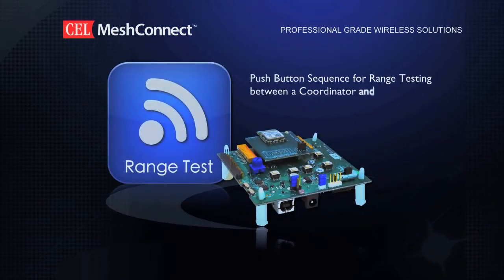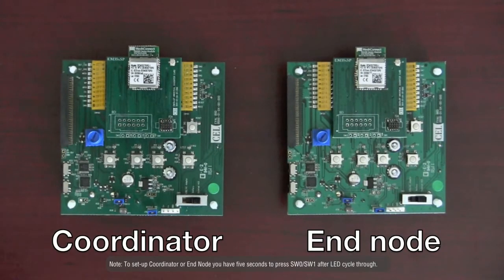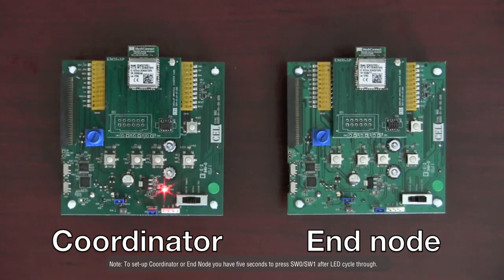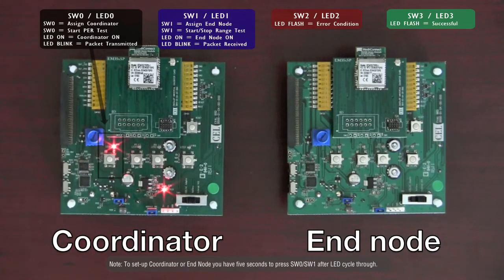Range test. Push button sequence for range testing between a coordinator and an end node. Here are two MeshConnect evaluation boards. One will be assigned the coordinator and the other the end node. We will turn on the coordinator by sliding the power switch to the middle position. You will see the LED lights cycle. Next, we will press and release SW0 and an LED light will illuminate. This will indicate that a network has been formed properly.